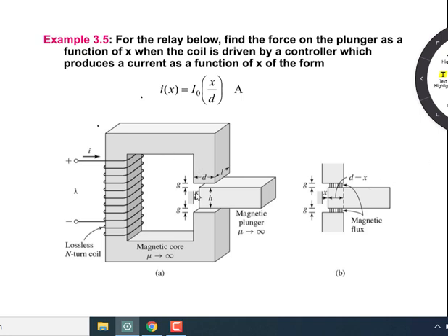What you will be able to figure out is that if we move this plunger away, then what would happen? You can understand that the amount of EMF that must be produced by the coil will be very high, because this is actually a series circuit, and when this plunger is absent or not in this gap, your EMF has to overcome the air gap path of high reluctance in order to produce a certain flux.